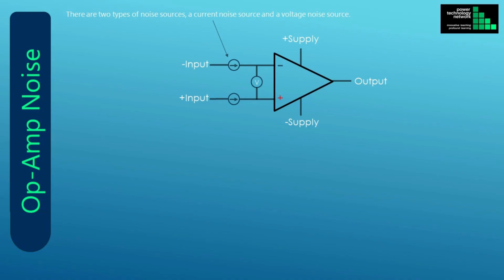Keep in mind that many op-amp applications require the amplification of signals in the nano and microvolt range. The op-amp noise sources produce noise signals in the nanovolt range. This will contaminate signals in the nanovolt range. So in applications where low signal amplification is required, the op-amp noise figures must be taken into account. So, an understanding of the modeling and specification of these noise sources is necessary, and is covered in this section.